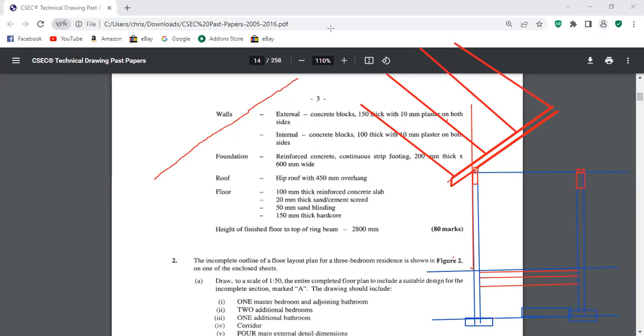You would nail your zinc onto this. So you then place your zinc onto this. The zinc should be a little bit like there. And then you would apply your nails. So you would nail here, nail there, to fasten the roof. That is one method. You have shingle roof, you have tile roof, you have other types of material that they use.